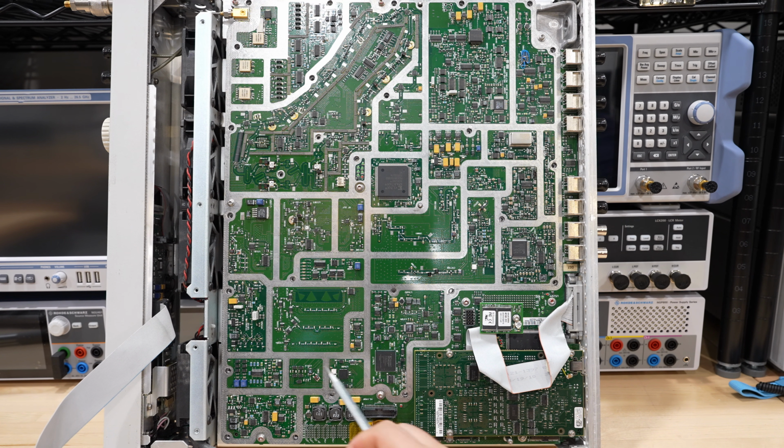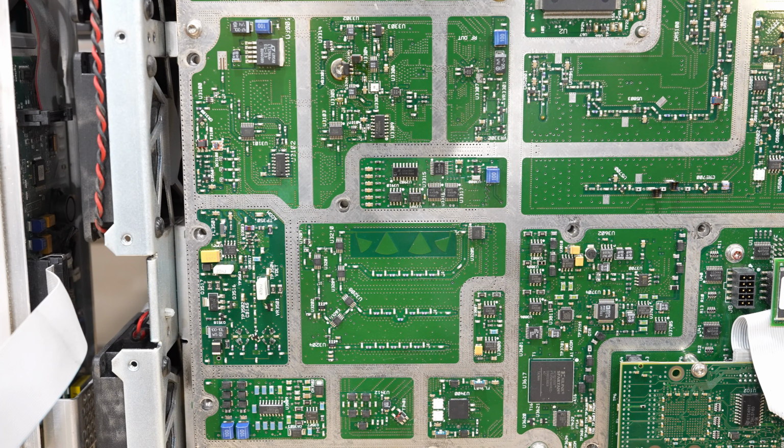So let's take a closer look over here so we can see which areas we really need to measure to see what's going wrong in this loop. And now with a closer look, we can analyze this circuit a little bit better. So starting from the VCO right over here with the discrete components and diodes used as varactors, we can even see a little label over here with a test point. That's the bias. That's most likely part of the loop. It's controlling the frequency of the VCO.